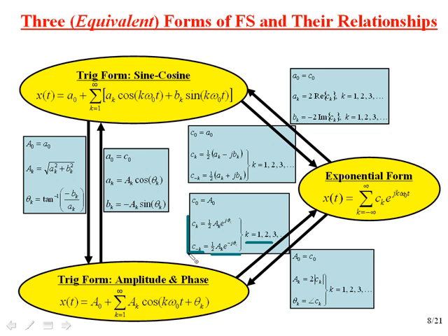Notice that these form complex conjugate pairs. So as soon as you form all the c sub k's for the positive k's, you know all of the c sub k's for the negative k's. So you've got c2, for example. c minus 2 is just the complex conjugate of c2. Okay, so that's very easy to do. Let me clear this up here again.